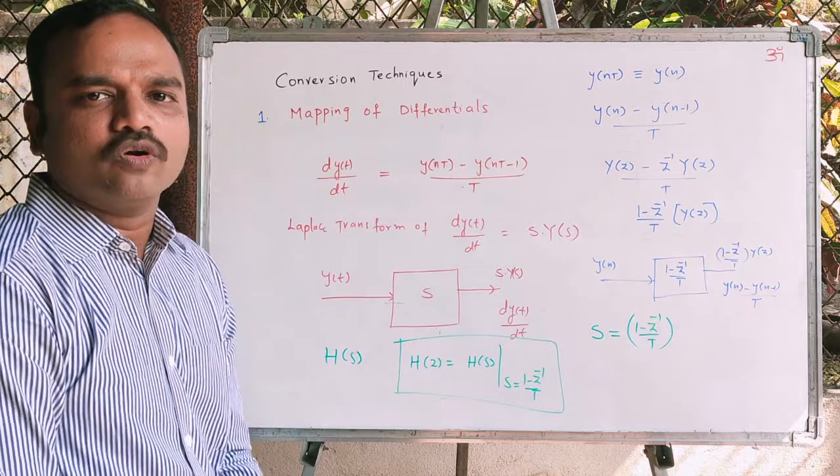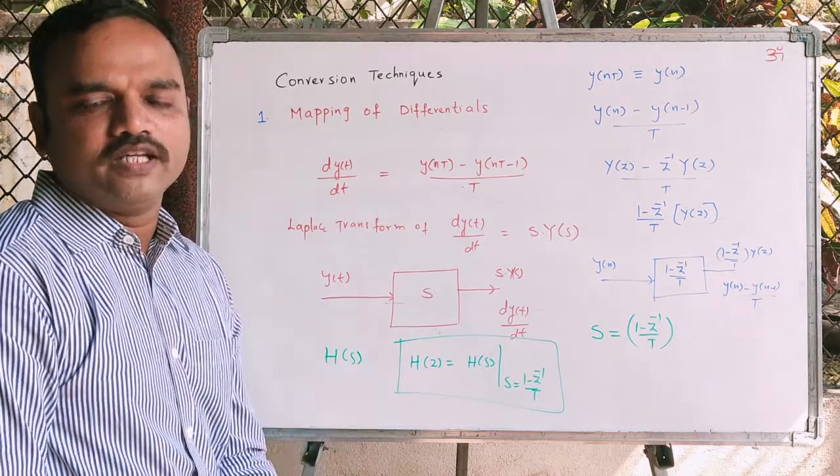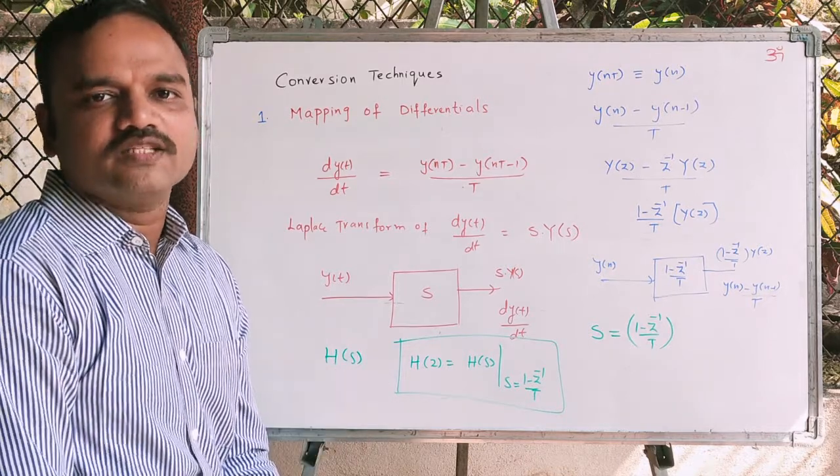This is the mapping of differentials, the simplest technique, which approximates the differentiation in the S-plane with the difference equation in the Z-plane.